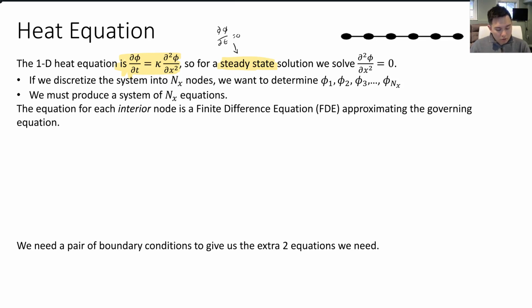And so the question is, how can we solve this for a particular system? Well, if we assume that we've been given a space that we've discretized using maybe 6 discrete points in space, with 2 at the ends, we can say that we want to approximate our temperature profile with temperatures at each of these 6 points.